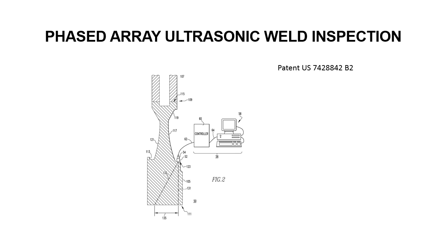So phased array is basically the old school ultrasonic testing, but they've hopped it up by using a bunch of small transducers, which each shoots out a sound wave independently. Then that information is taken back to the computer, and it gives you an image. Similar to medical testing. That's phased array, I'm pretty sure.